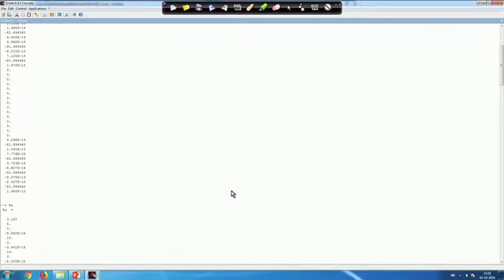You can solve some other different problems using the code and check your solution with other software. Also you can do some exercise like changing the Young's modulus. Suppose you have a truss where you have 100 members, and make one member very soft, in the sense you reduce the Young's modulus of that one member drastically, and the rest of the members' Young's modulus are the same, and then check what the behavior of the truss is.